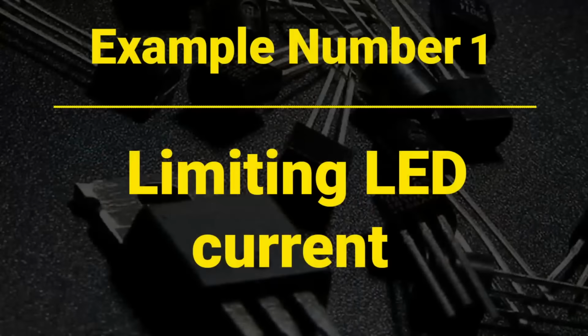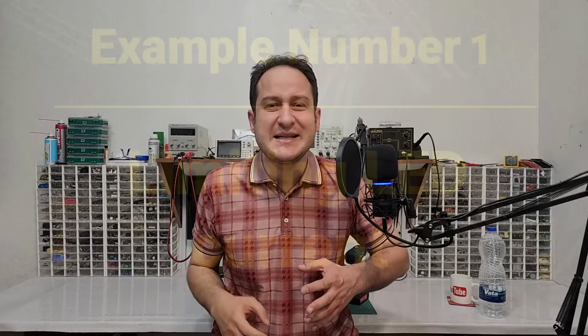Let me give you the first example, which is so predictable. Example number 1, limiting LED current. This is the simplest example of resistor usage ever. We can't connect an LED directly to voltage sources like 5 volts because the forward voltage of an LED is much lower than 5 volts. Connecting 5 volts to the LED will try to draw infinite current, and this will destroy the LED. We have to put a resistor in series with the LED to protect it from overcurrent and burning.